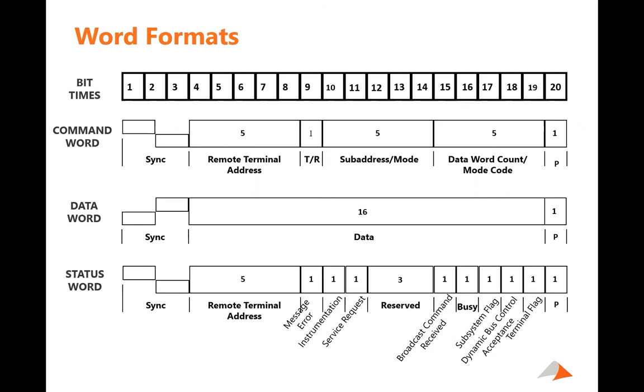Very good. So these are all set up in messages, and you'll see that in just a minute. Your good lead-in, actually, is that data words always follow contiguously after a bus control message if the RT is to receive data.